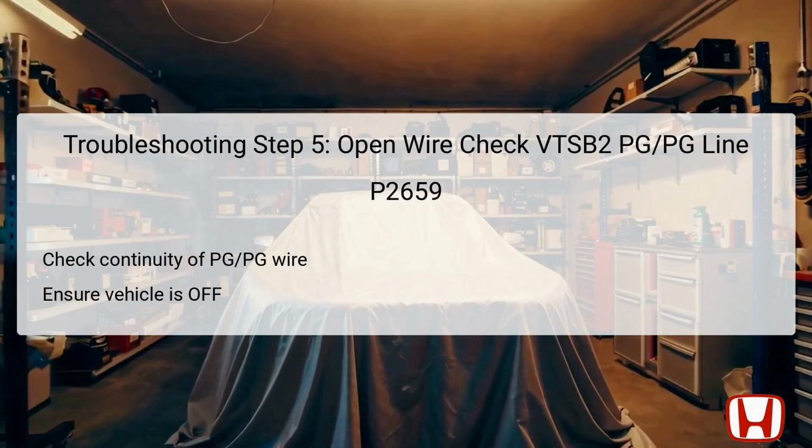In troubleshooting step 5, the technician is required to perform an open wire check on the VTSB2 PG line. This process begins with the vehicle in off mode and the rocker arm oil control solenoid A, bank 2 connector remaining disconnected. The continuity between the designated test points must be checked to ensure that the PG wire is intact. Establishing continuity indicates that the wire connecting the solenoid to the body ground is functioning correctly.